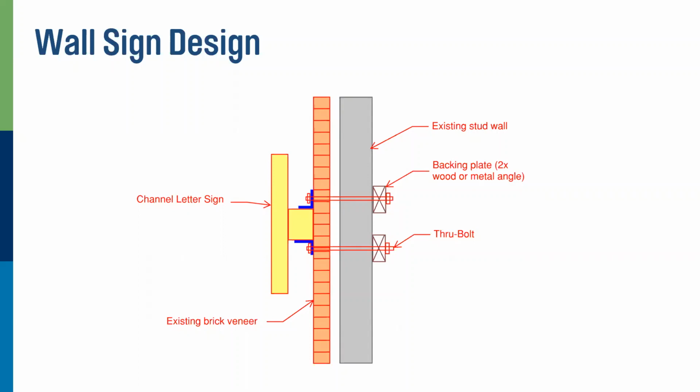And I'll tell you the main reason for that is because although it's just a 1/8 inch difference, there's actually a big difference in capacity, and a 1/4 inch bolt or screw, a fastener, can shear off fairly easily. 3/8 inch doesn't shear off as easily. If you already have your clip angle right there and you drill that hole and start screwing it in and it shears off, now what? Now you've got to put another clip somewhere else, and hopefully you don't hit something behind the wall that's in the way. So that's why you have larger.